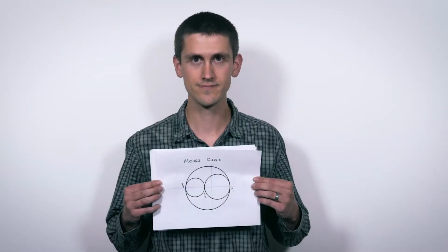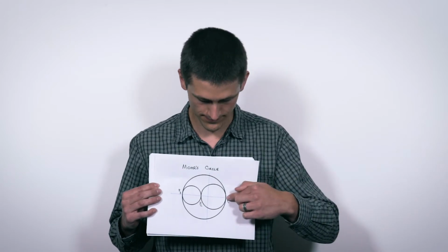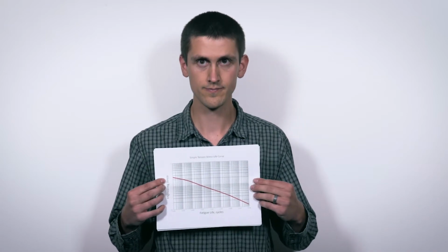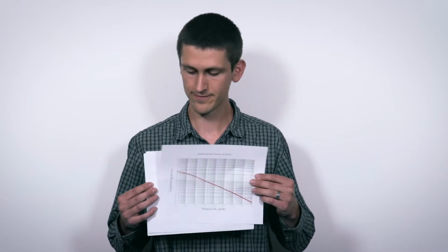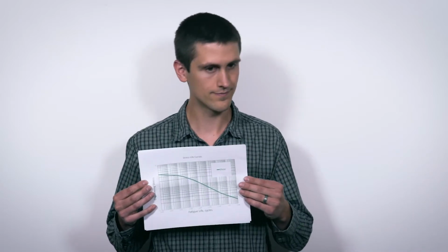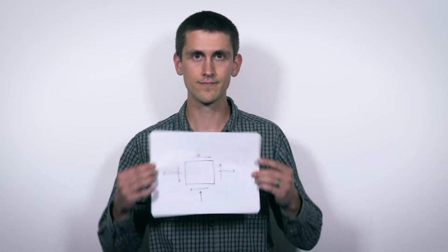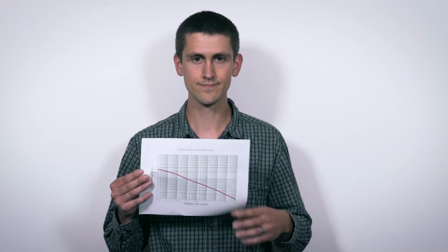That's trickier. You could try looking on your uniaxial fatigue curve at the stress that is equal to the max principal stress. This can work when the loads are tensile and the loading direction doesn't change much. But the tension fatigue curve isn't the same as the compression fatigue curve, which isn't the same as the shear fatigue curve. Also, if your loading direction changes dynamically, it causes damage, even if the amplitude of the max principal stress is 0. A uniaxial curve just isn't enough information to get the job done when we have multiaxial loading.